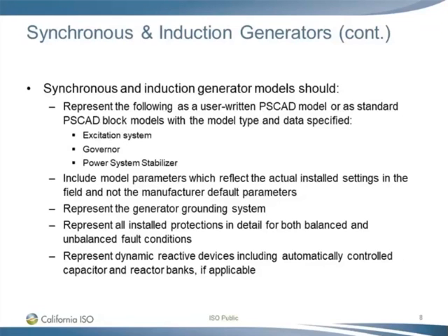All synchronous and induction generator models should also represent the following components as user-written PSCAD models or as standard PSCAD block models with the model type and data specified. The applicable components are the excitation system, governor, and power system stabilizer.